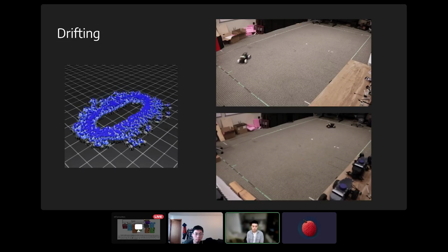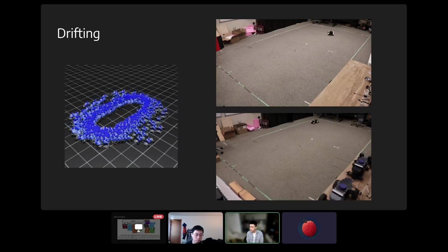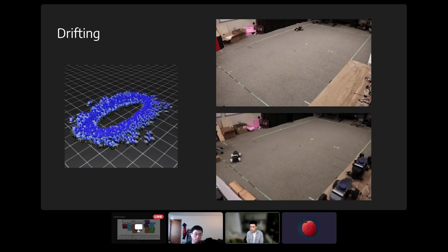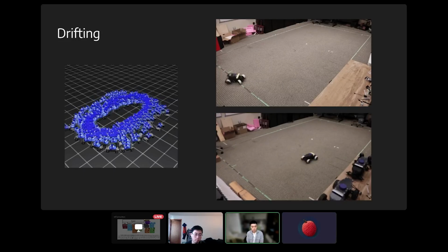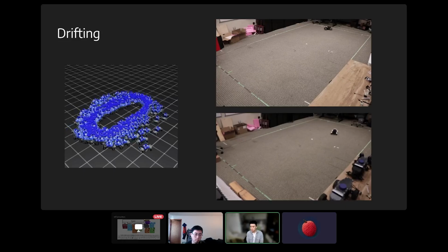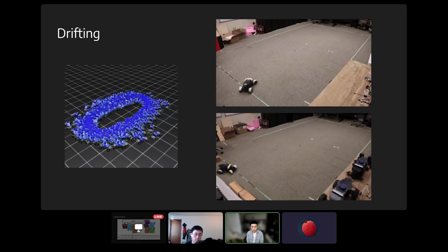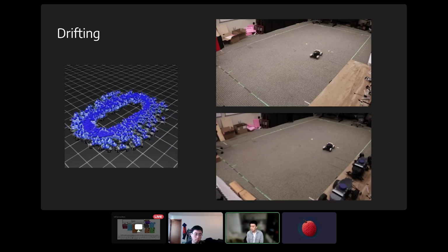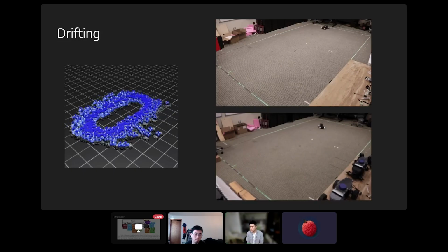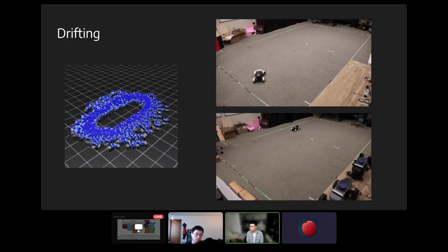So if you train a model in simulation, it rarely transfers directly, and you have to do some tricks. Domain randomization will change up, like you said, the friction or the mass, to cover a bigger space of potential real world settings. At least this is the theory.